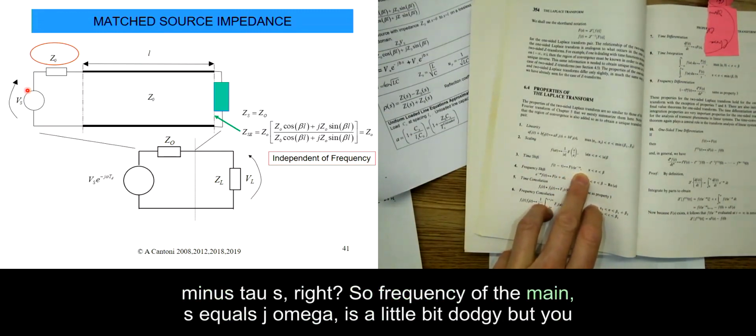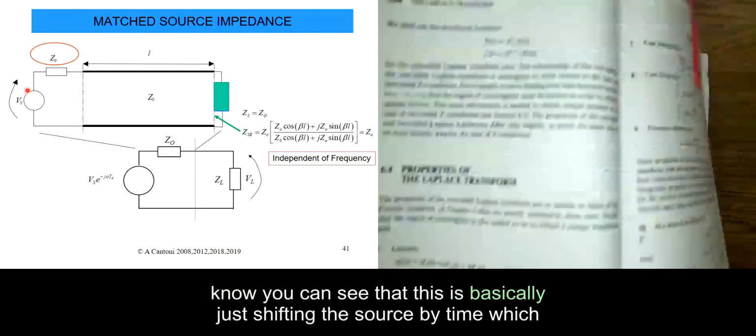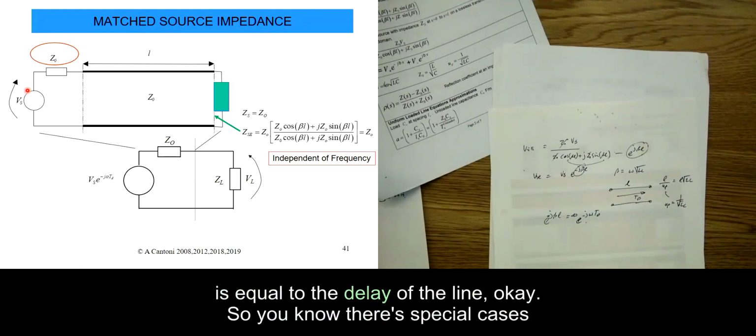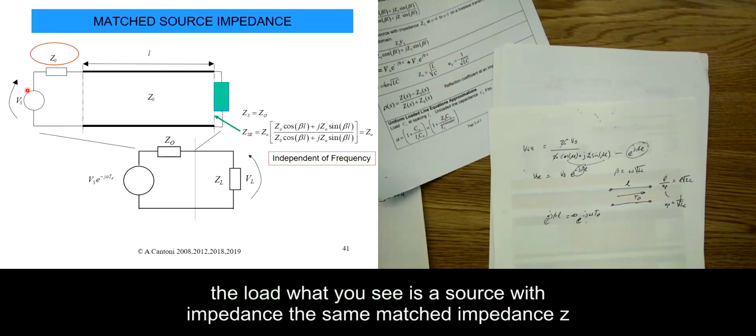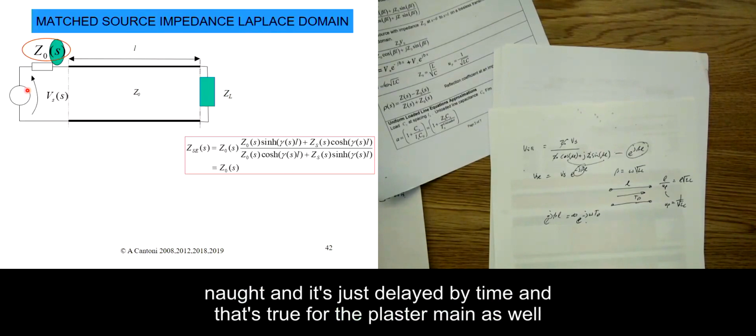Okay, so frequency domain, s equals j omega. It's a little bit dodgy, but you can see that this is basically just shifting the source by time, which is equal to the delay of the line. Okay, so there's special cases where you have a matched source impedance. Effectively at the load, what you see is a source with impedance, the same matched impedance Z0, and it's just delayed by time. Okay, and that's true for the Laplace domain as well.